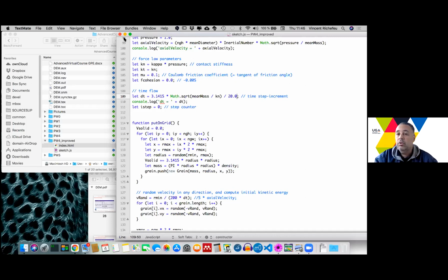Okay. You can also consider coupling as a multi-scale simulation. Like you can couple FEM with DEM by making FEM, and instead of having a constitutive law at each Gauss point, you may have a simulation. I'm not sure I completely answer the question, but of course you can couple, and you should, because granular materials are not always dry granular materials. They are actually more complex. So depending on what you are studying, you will need to couple for sure. Okay, good.